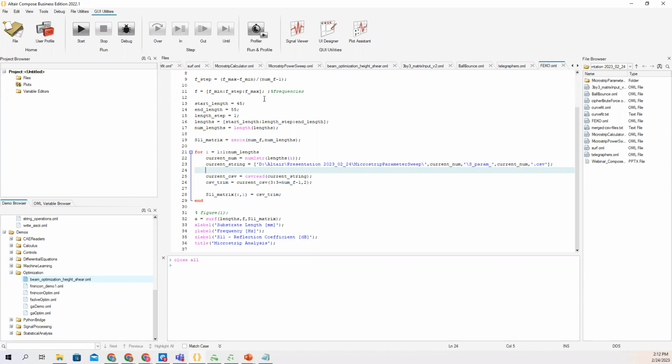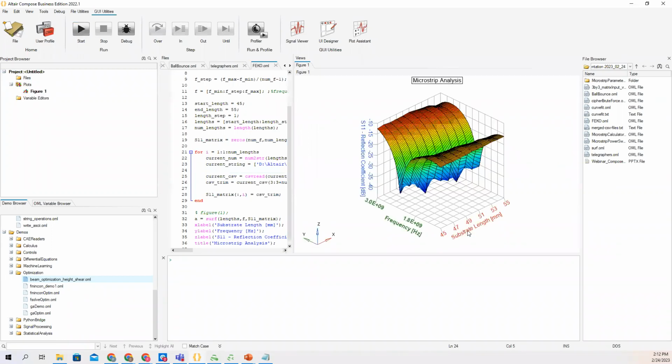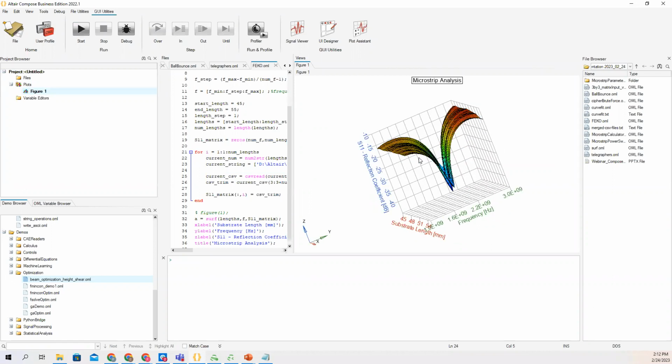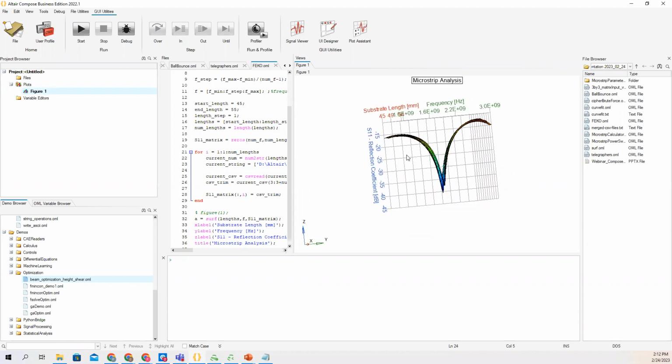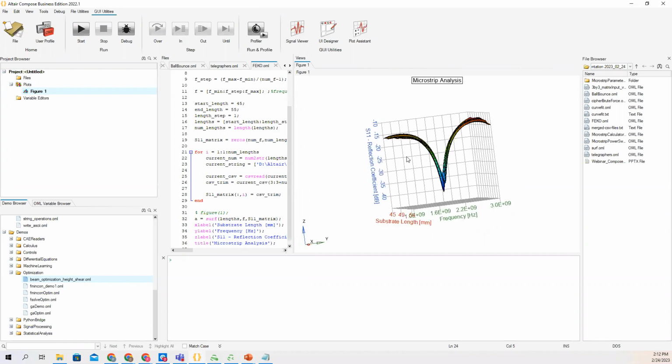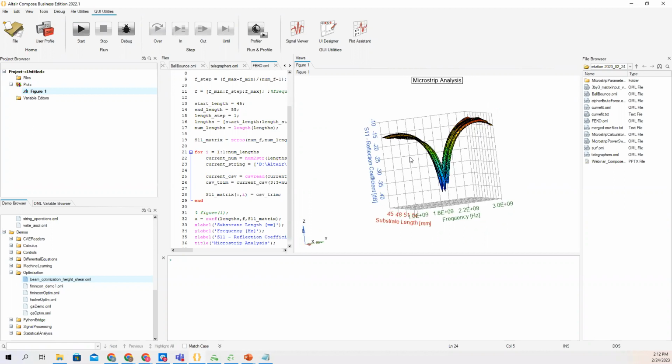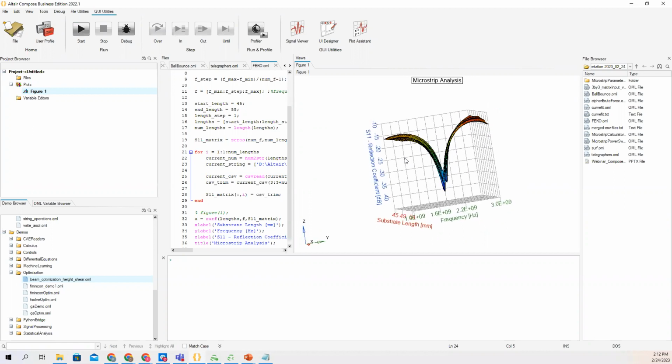So we can pull all of these S parameter numbers that are extracted from FICO and plot that in 3D. That's exactly what we've done here. And we can see, if we look at this head on, it looks like our standard, if you're familiar with S parameters, an almost ideal waveguide or transmission line when we're looking at reflection coefficients.